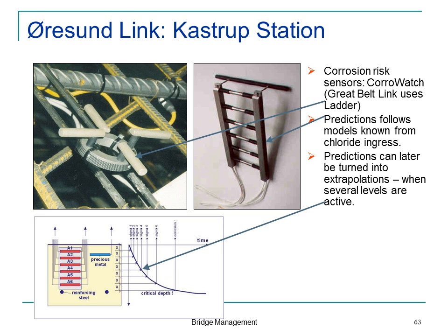So install sensors, and you can actually inspect the otherwise non-inspectable areas. And with these things, we know the reference sensor has been used for 30 to 40 years. It seems to be doable. The other parts of it, well, that's plain cathodic protection, we know how doable that is. And with this, we will get a very good warning before there are problems, if there are ever problems.